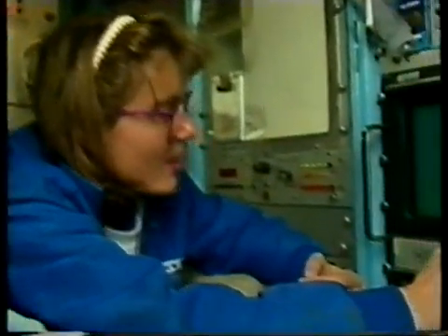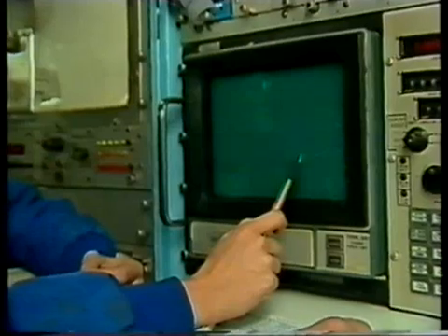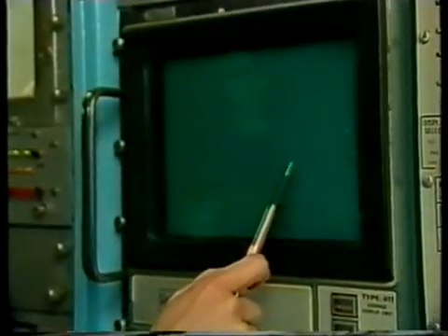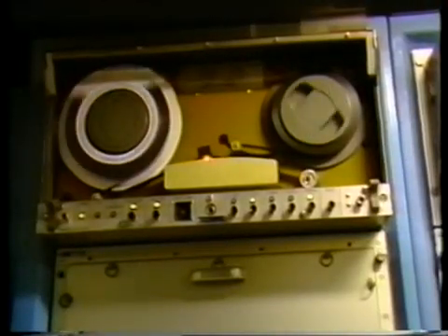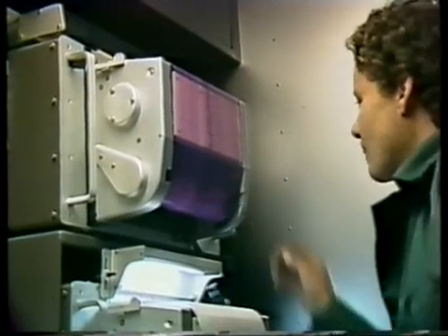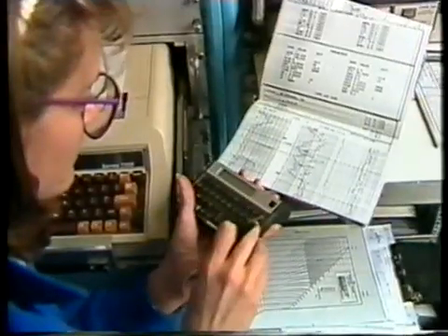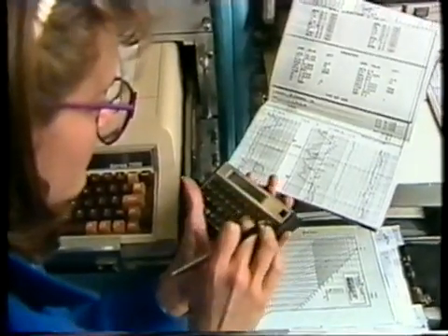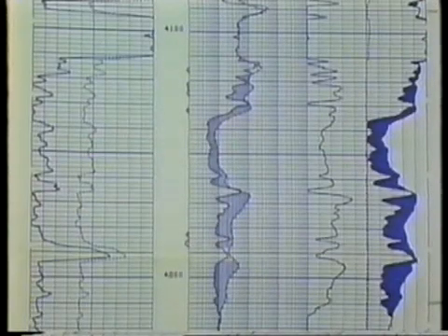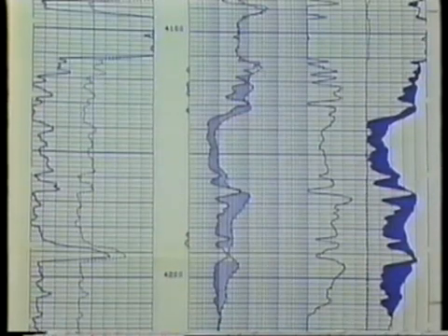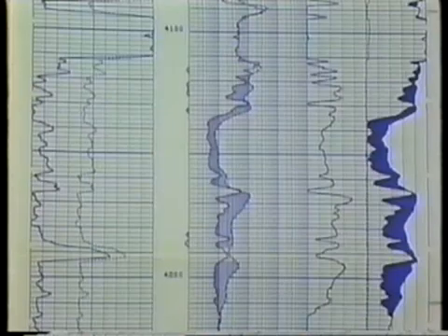As the string of tools moves uphole and passes through possible prospective intervals, the oil company representative studies the evolving curves with the logging engineer, and, if necessary, asks for a rerun over critical intervals. As logging proceeds, a permanent record of digital data is made on tape, and a visual record of tool responses is made on film. At the end of the run, the film is prepared on board the unit, and further on-site evaluations can be performed. Digital data are often evaluated and integrated at the well site through quick-look computer programs on board the logging unit.